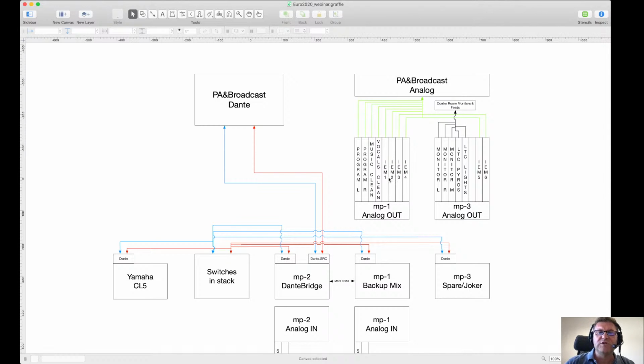And then 4 or 6 different in-ear monitor feeds managed by the Yamaha CL5 in the control room. 4 of them were for Bocelli, his wife, and the 2 football players. And in-ear monitors number 5 and 6 were for performers, such as the tambourine bands and the marching bands and other stuff. Those ones were feeding FM transmitters because there were a lot of receivers on the other hand, and therefore they were receiving FM transmission. But from our point of view, basically we could consider them 6 mono in-ear monitor feeds.